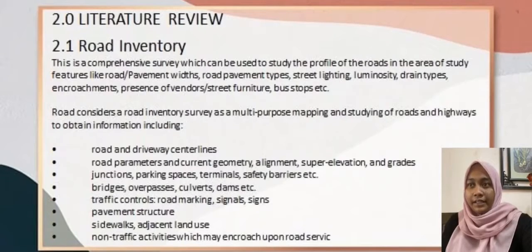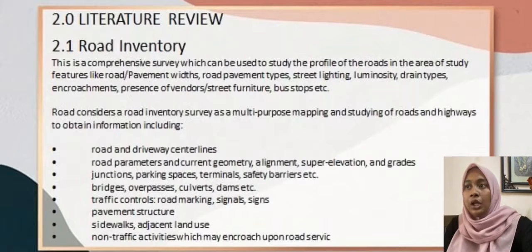Road inventory. This is a comprehensive survey which can be used to study the profile of the road in the area of study, with features like road or pavement width, road pavement type, street lighting, luminosity, drain type, encroachment, presence of window or street furniture, bus stop, and ads.